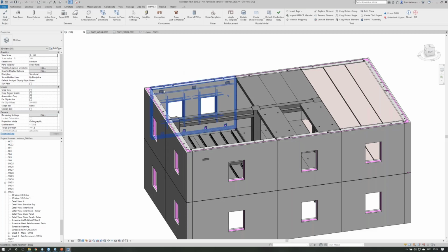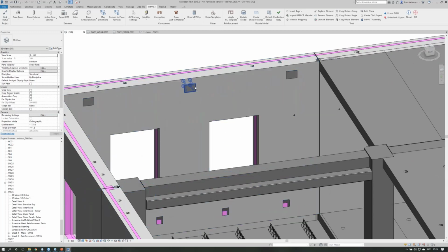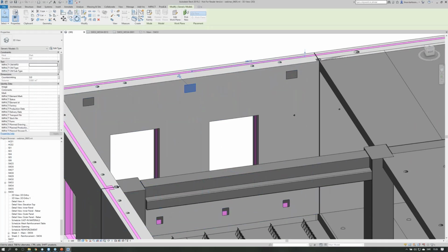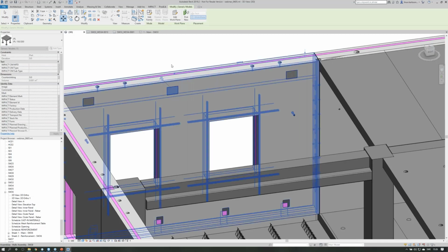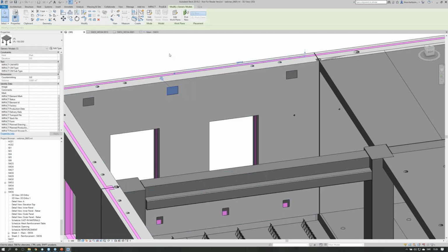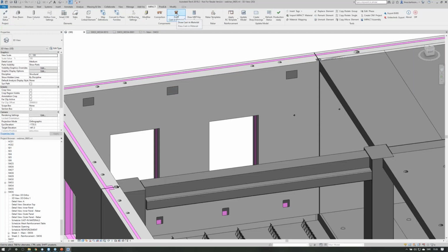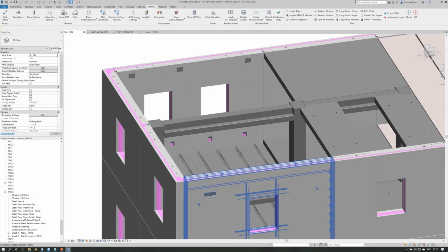Whenever that's done, I can manually move it however I want to, because each are individual instances now. So the rules are basically just used when you apply the cost materials, and when that's done, it is basically the same as if you had inserted it through the draw cost materials as I showed in the beginning with this cost material created.